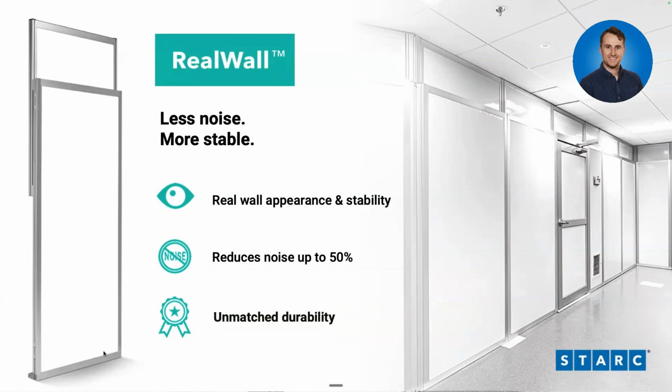RealWall is a modular reusable wall that has multiple width panels, and you simply bring panels together, lift them up, drop them together, and that's what locks them together. And it's built with a lower panel and an upper panel that you can telescope the upper panel to reach various ceiling heights. So it has that modularity built in. And really, you only need a 5/32 T-wrench to install these.